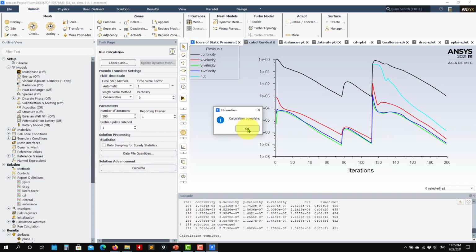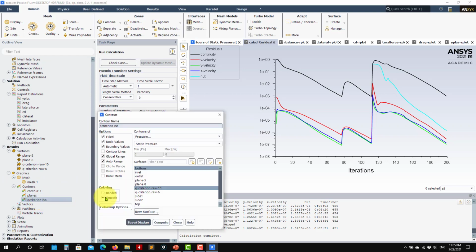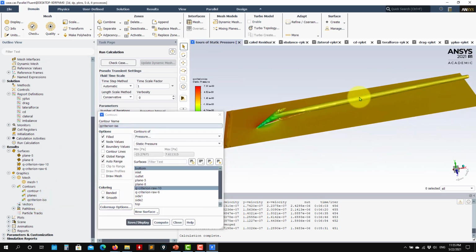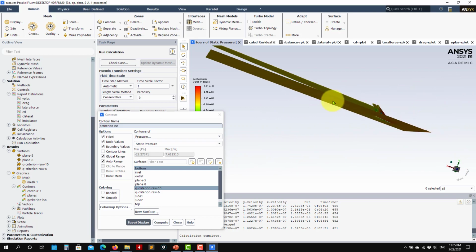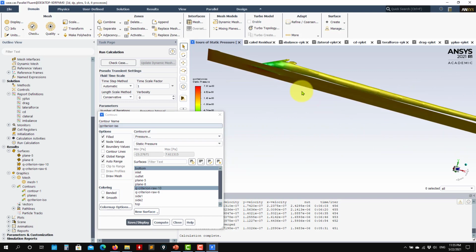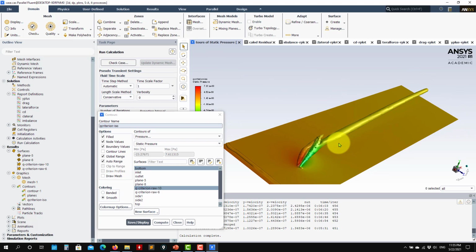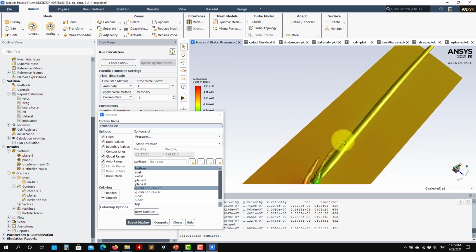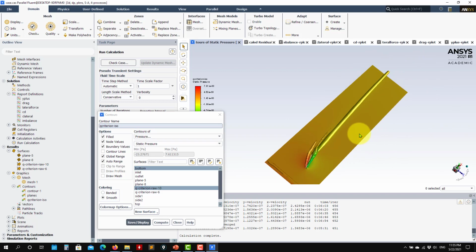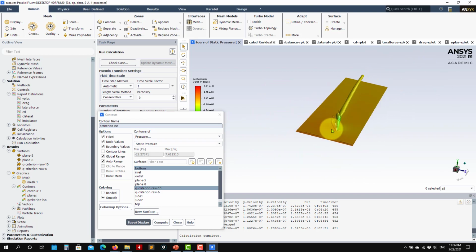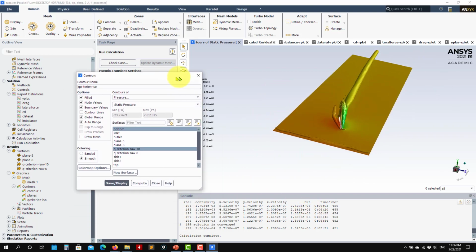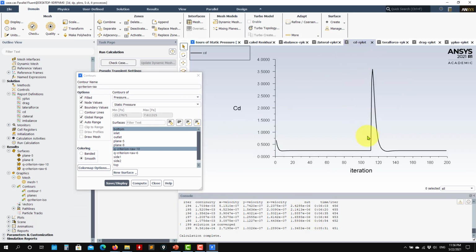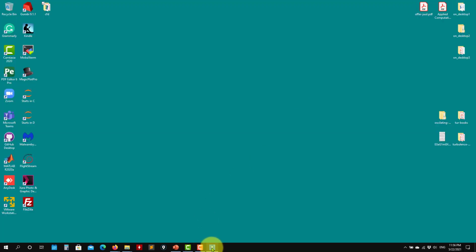Okay, we reached the final tolerance, and again, let's go here, and I just want to plot this one and see that we have a nicer vortex there. Remember, using the same criterion, you can compare all the methods, K omega, K epsilon, you will see that this one captures this vortex better. Also you should quantify. You will see that your CD, CL are similar in all cases. You have here the whole evolution, so you see that there are no big changes. But again, this is something that you should quantify.